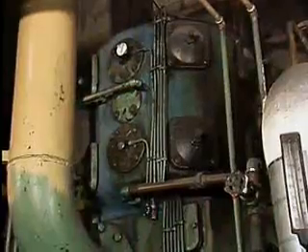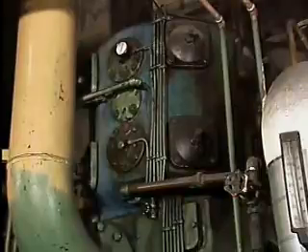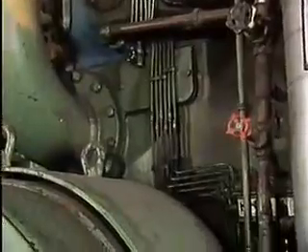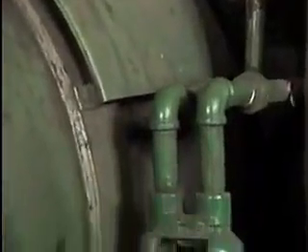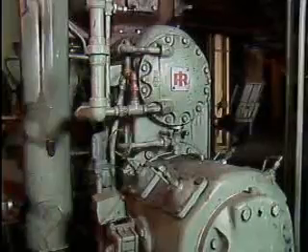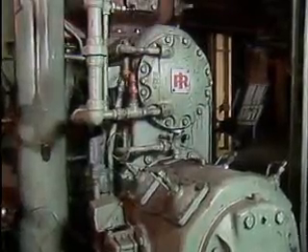Water cooling can be accomplished in two ways. One way is to use jackets. A jacket is a chamber that surrounds the compressor. Water is circulated through the jacket to cool both the compressor and the gas inside it. The other method of water cooling cools just the compressed gas.